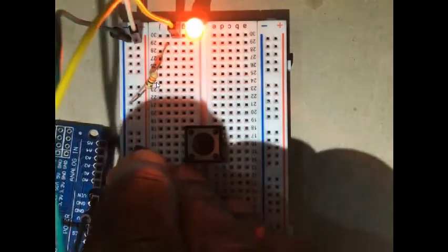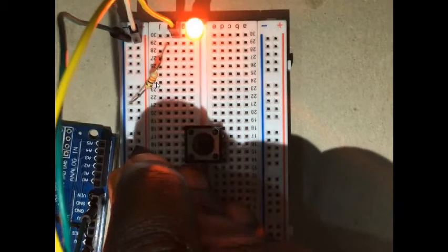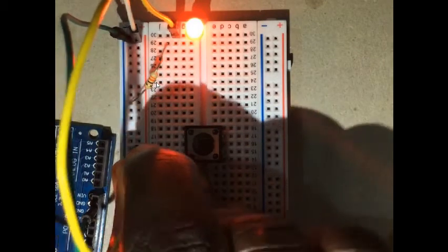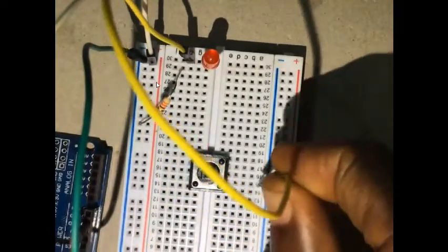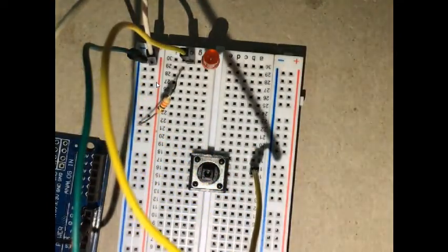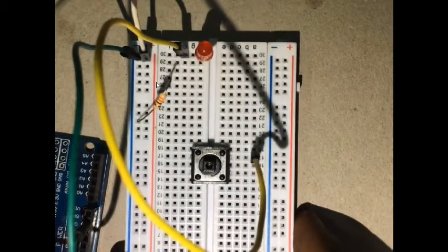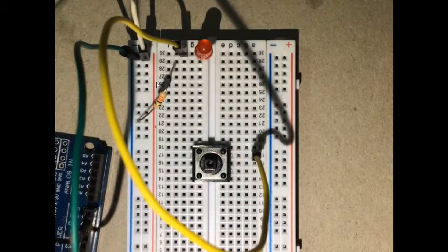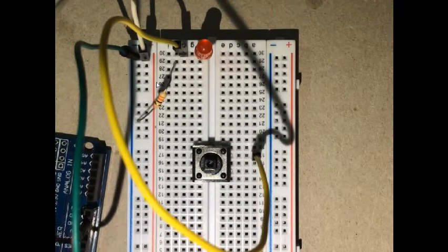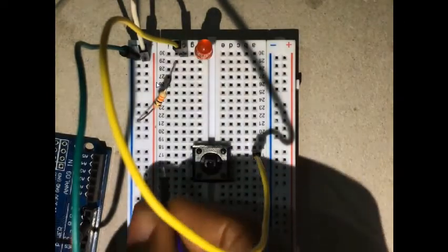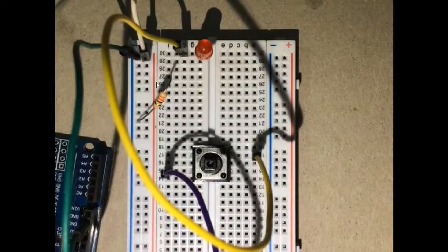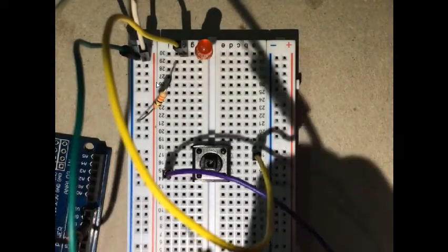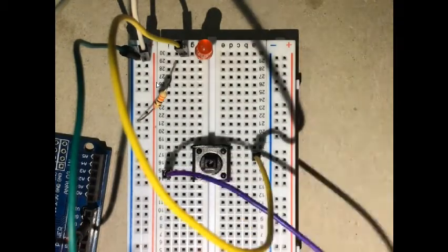So this is the wire that connects the anode to 5 volts. I'm going to remove it now, and you can see that the LED has gone off. Is that correct? Yes. So I'll plug this wire to one of the leads of the button, the one on line 17. Then I would bring in another jumper wire. Let me use a purple jumper wire, and I will connect it to this lead, and then connect the second end of the jumper wire to the 5 volt rail.